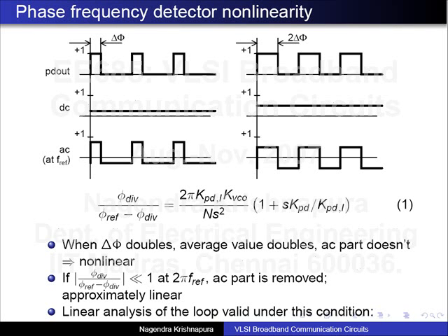This is okay? When it has to lock, this will come into it. Which will? But the PLL is yet to lock. No, so this is even after locking. But before locking, it is definitely nonlinear. The capture process is nonlinear. This is a problem for analysis, not necessarily for the operation of the PLL. So we don't use linear analysis for analyzing capture. We use it only for lock and then some small changes around the lock. So then it is okay.